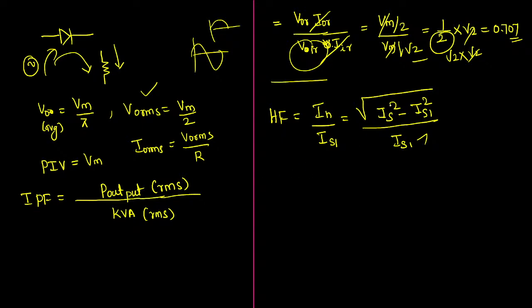Similarly, the source current will not express purely the fundamental current alone. It will be expressing fundamental plus harmonic current. Harmonic means all others. It can be a DC component, or a third harmonic, fifth harmonic, seventh harmonic, second harmonic, or fourth harmonic effect, whatever it is.